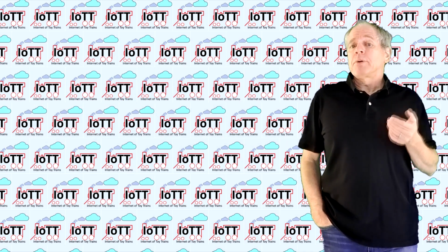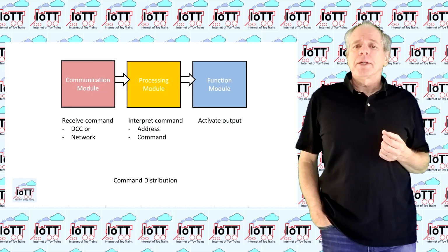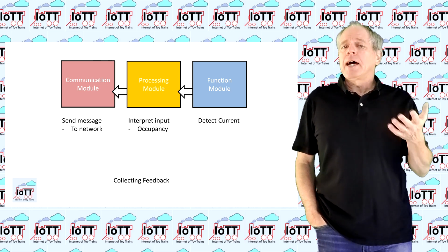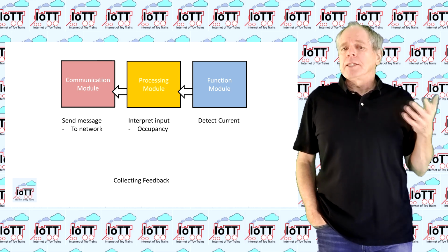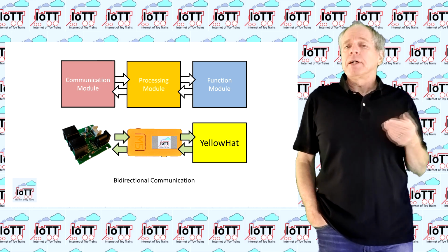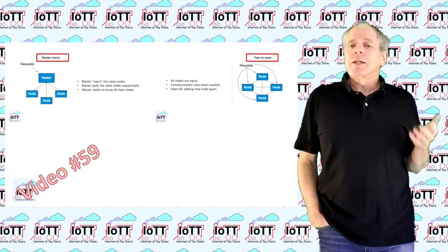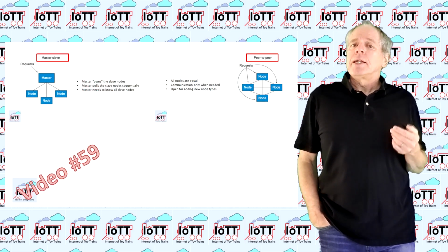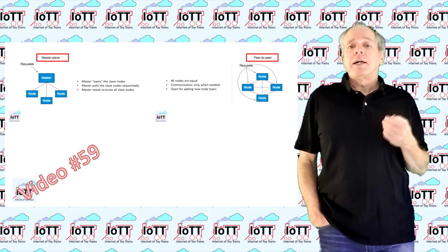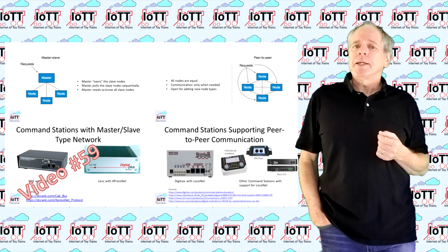Now, if this already provides a lot of flexibility, there is even more you can do when using Loconet communication. The main difference, of course, is that Loconet is a layout control network, which means it is bidirectional and messages can flow in both directions, other than DCC, where all information comes via track from the command station. What makes Loconet the control network of choice is that it has everything needed for layout control, is reliable, has very little administration overhead, but still is an event-based peer-to-peer network.